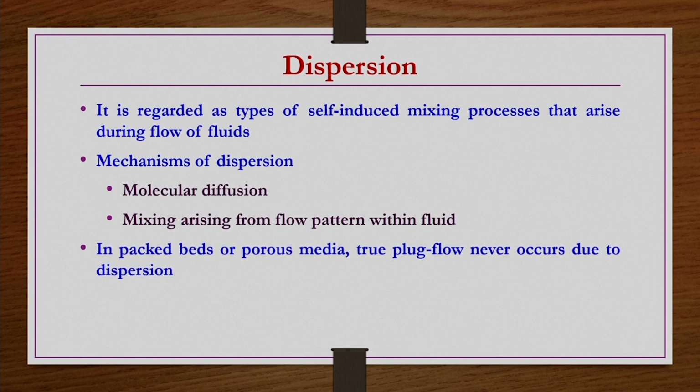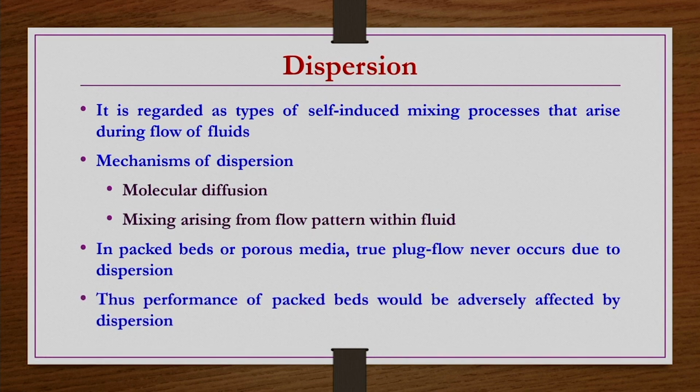In packed beds or porous media, true plug flow never occurs due to the dispersion. Obviously, if there is dispersion, we will never have a true plug flow, and because of that, performance of packed beds would be adversely affected by the dispersion. So, why dispersion is so essential in the case of packed beds, that we see.